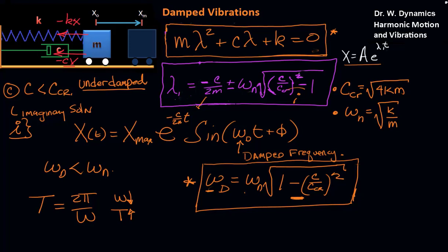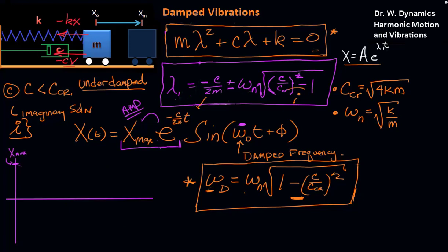Now if we look up here, the e function here is decaying the amplitude of this, and that's what's happening in front. And then the natural frequency has been damped, so it's taking longer for it to make a period. So two things are happening. If we look at the motion, the amplitude itself due to the exponential function is going to decay like this.